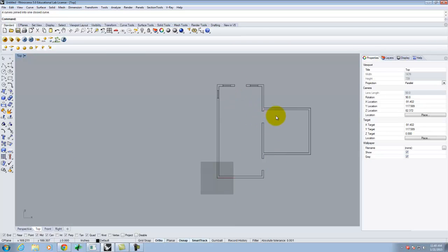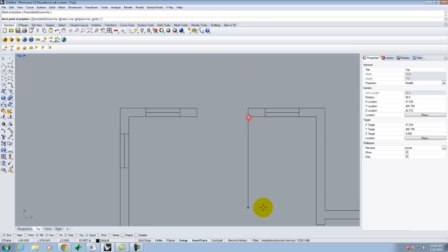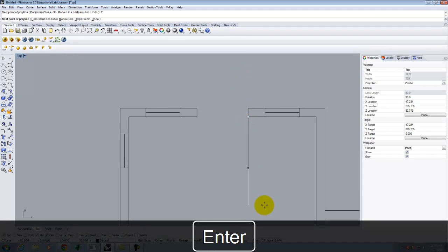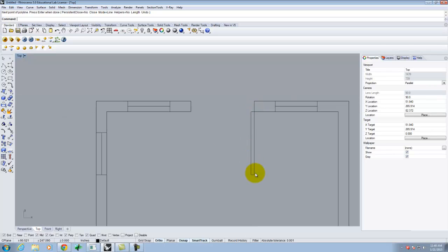Okay? So from here, it's a matter of adding more detail. There's more windows, there's doors, there's door swings. I'll show you the door swing, and then I'll turn you loose because it's a curve. So let me go ahead and draw the door. It's a 3-foot door, so I'll do 3 feet, and then it's an exterior door, so it's 1 3/4 inches in thickness. Though I'm not expecting you to know that. You can make it however large you want it to be. And so once again, I'm using smart tracking from that point there. So I have my door.